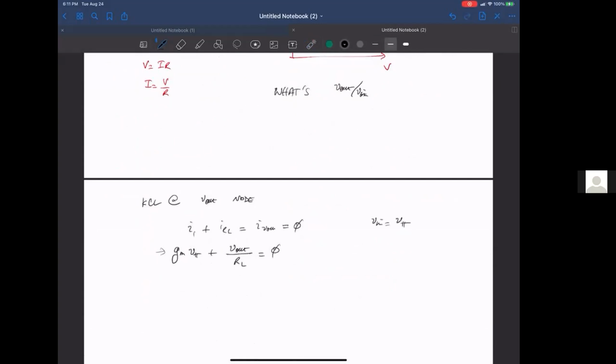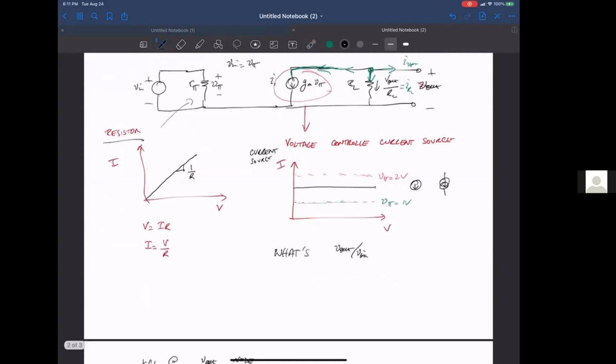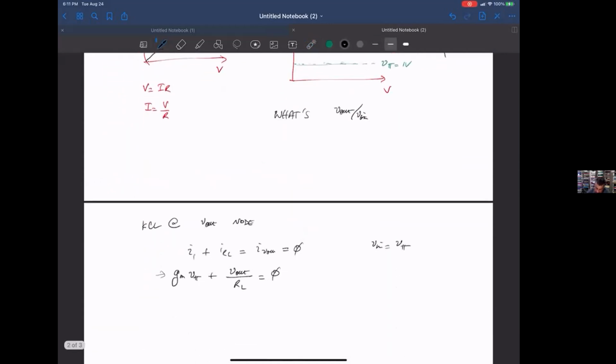I have a question real quick. Yeah. So when you did KCL, wouldn't the currents leaving the node be negative? Yeah, it just depends on the sign. So I think if you want to say like minus I sub 1 minus R sub L is minus I sub out, you could do that too. Okay. Yeah. So I think strictly speaking, you're correct. Thanks, Ellis.